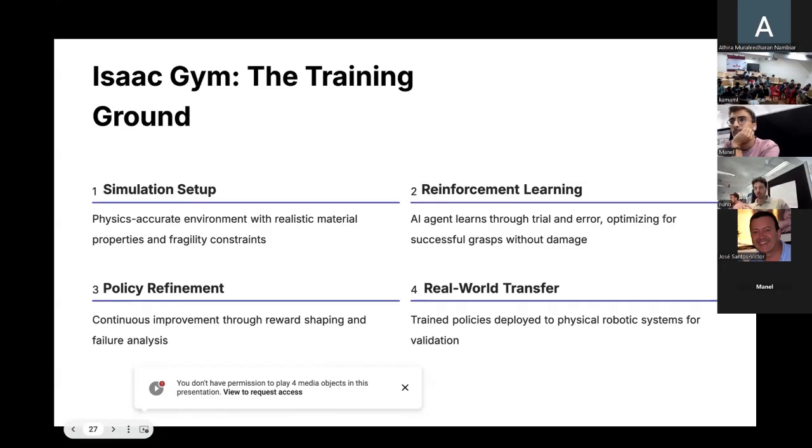And then, of course, we run reinforcement learning with trial and error, multiple times, multiple environments, multiple configurations of where the pieces are, or where the pieces should go, of how the arm could be configured, so the policy can learn how to adapt to multiple locations of the objects, multiple target locations, and multiple sizes of the objects, because we're going to have a plethora of different fragments.